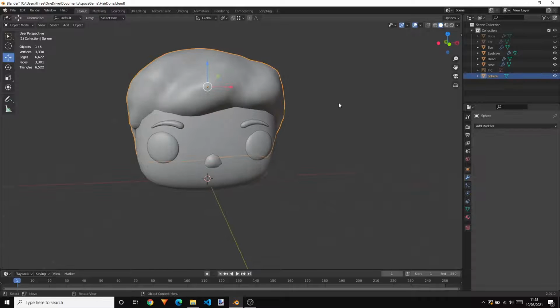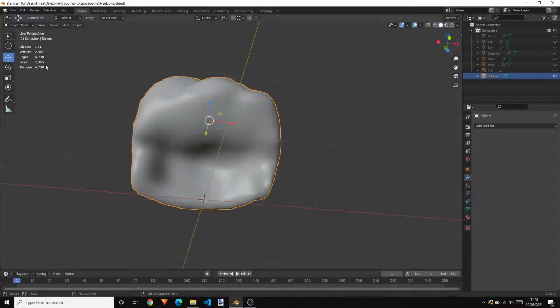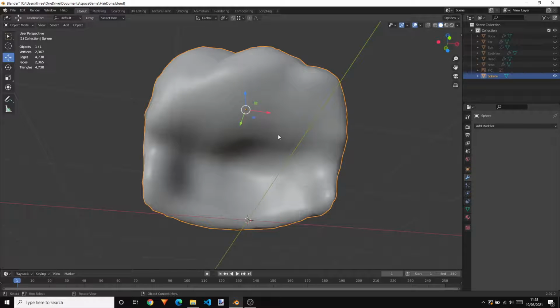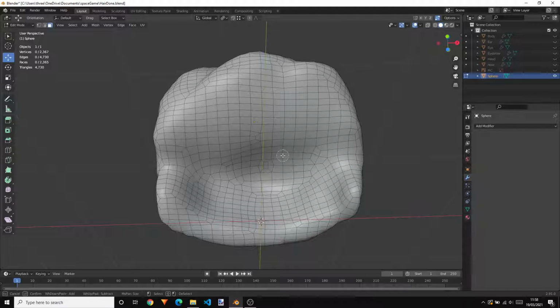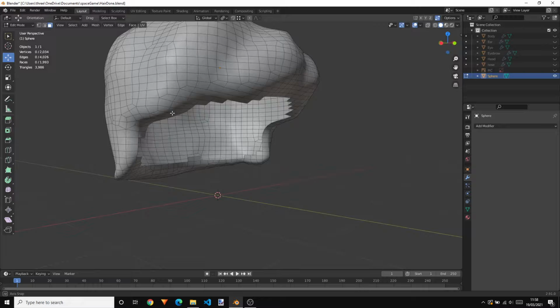Let's go to the sphere for the hair. Let's have a look. Yeah, the hair is taking up 2000. So I'm going to go tab into edit mode and then circle select with C, use my mouse to make it bigger, or smaller, and I'm going to just try and select some of these faces inside. Got to be careful that that's not visible. So I think that'll probably be okay. Press enter and then X to delete faces, and now we're down to 3900.